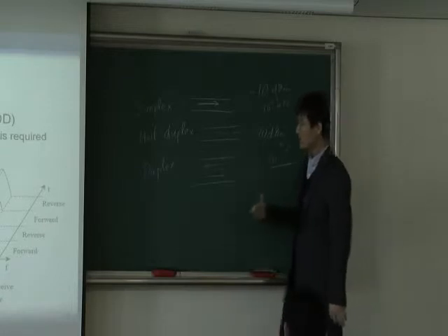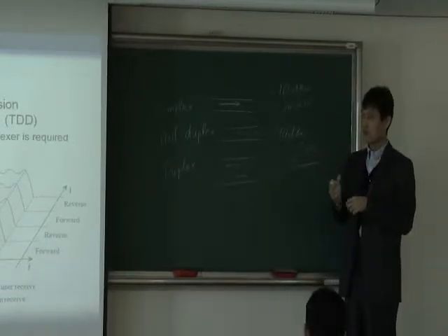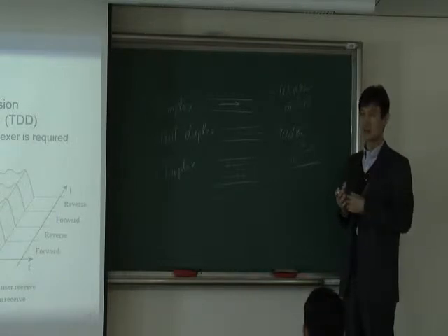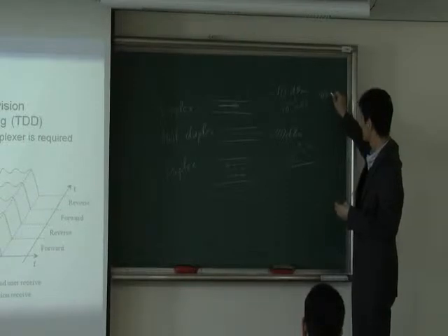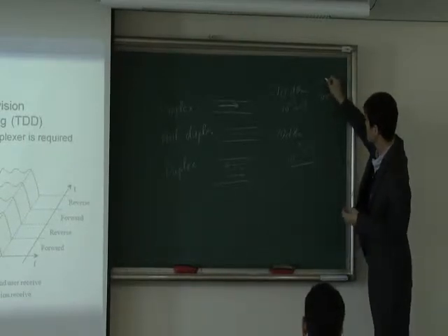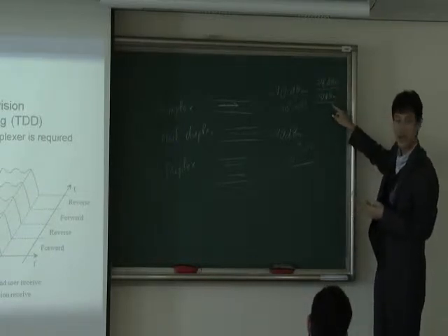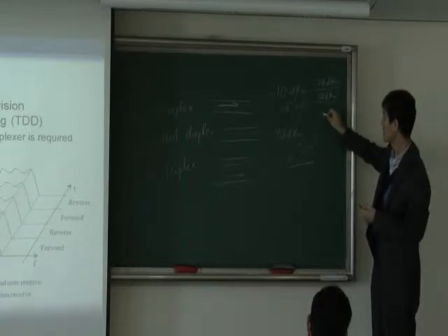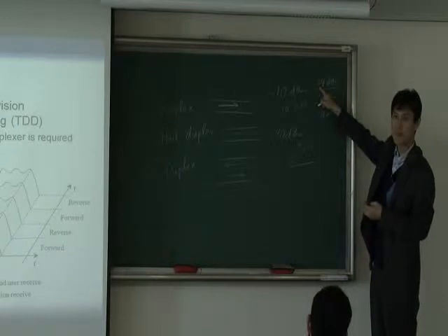Now let's think about your transmit power. Your cell phone can transmit sometimes like 10 dBm. Not minus 10, just 10. Maximum typically it's 24 dBm. This is extremely high power compared to this, right? It's like 10 milliwatt, or more than 100 milliwatt. It's like 300 or 400 milliwatt.